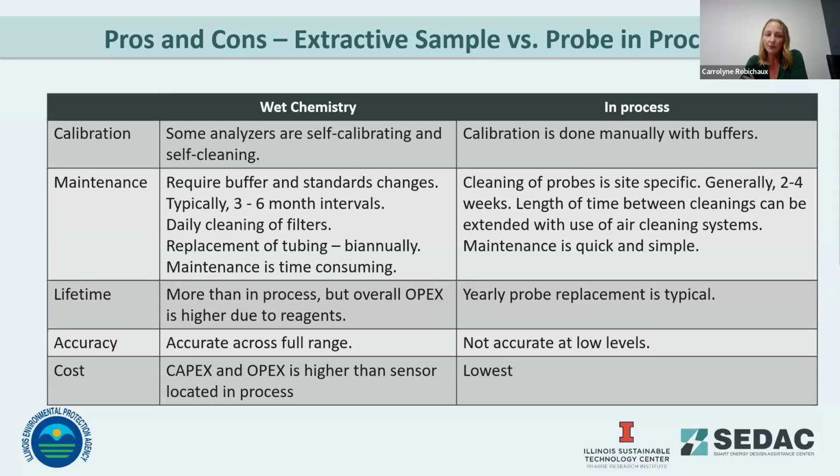And then an in-process analyzer, though, as Sean mentioned, and I mentioned before, say if you're looking at an ammonia measurement, you are not able to read below 0.5 ppm, where a wet chemistry analyzer can all day long.